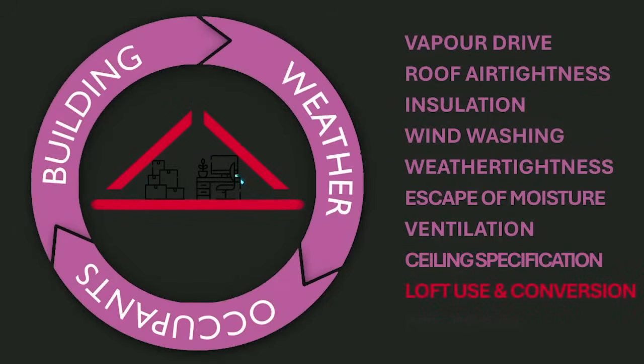Finally, vents may be inadvertently blocked by stored items in the loft, or purposefully blocked by homeowners who may not fully appreciate the importance of this airflow, choosing instead to block up the drafts to warm the loft up. Any subsequent loft conversion may be complicated by the need to maintain good airflow. Adopting a fail-safe approach to moisture management reduces the potential for long-term problems to arise in the roof construction, either as a result of upgrade or conversion work or arising from repairs and maintenance.